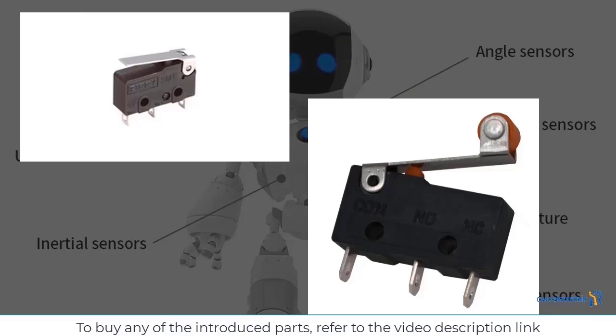and the arm may move a little more or a little less than the desired amount. Especially if we want to do something sensitive with the arm, the problem will be more obvious. This is where the use of microswitches can be very useful. Their use is such that the microswitch is placed in the arm or the place where the arm is supposed to move so that when the arm reaches the place, it activates the switch, and this activation sends a signal to the controller, which results in immediate operation.